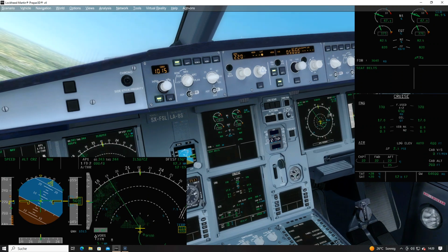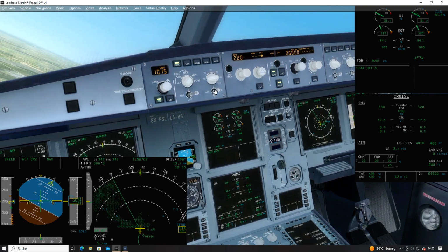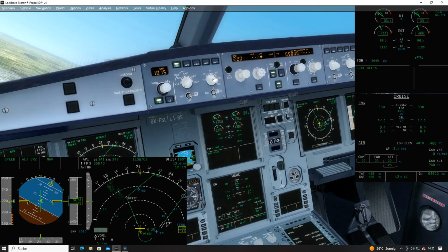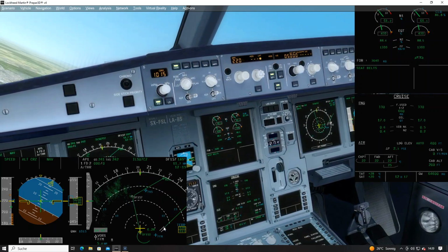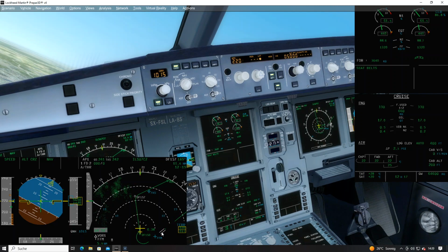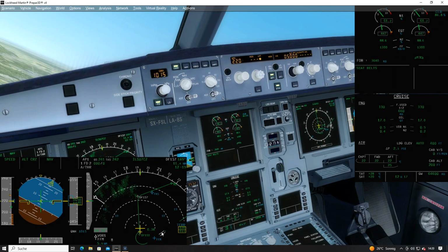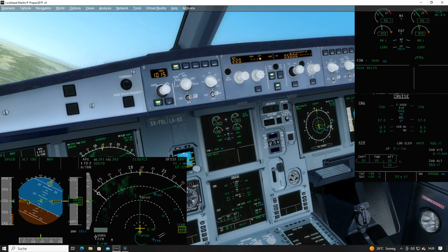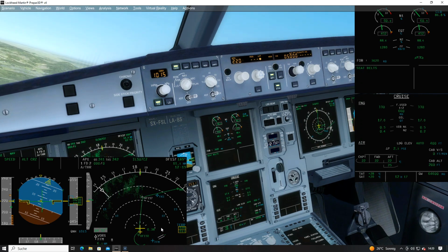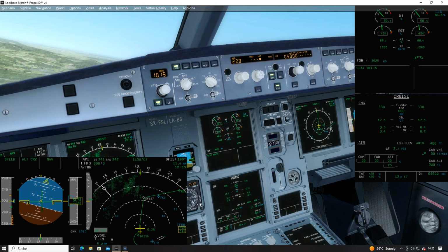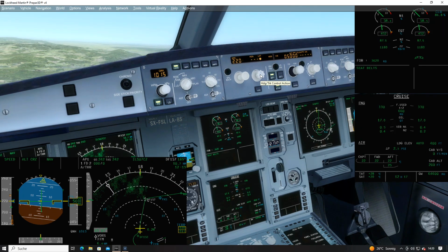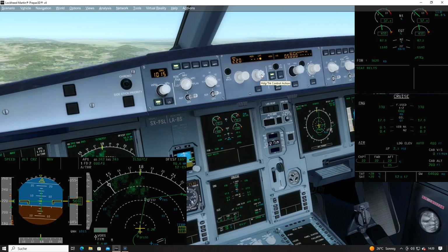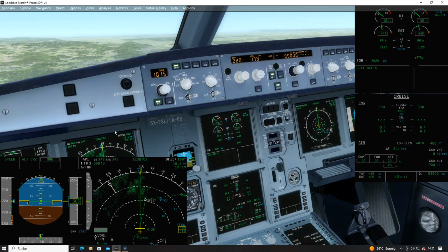Now we're turning to the south. Change the range on the nav display. You can see here on the right hand side the double white stripes, which is the runway for landing, and basically that's the direction we want to go. So as with a flight management system, we can also select a lateral deviation. So we pull the heading back, the mode has switched to heading.